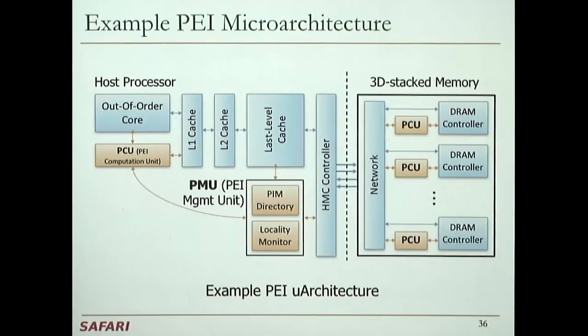Somehow. Yes. So is it like making it a dirty block? Not really a dirty block, because it's not really dirty, right? It's basically you're locking it in the cache. You have a bit saying, I'm locking it, no one else should access it. We'll talk more about cache coherence. We'll go into the details. But that's essentially it. If you think about locking, you're locking a cache block in hardware. Because you don't want to have it in the cache also. You're not going to fetch it into the cache. It's really over here.